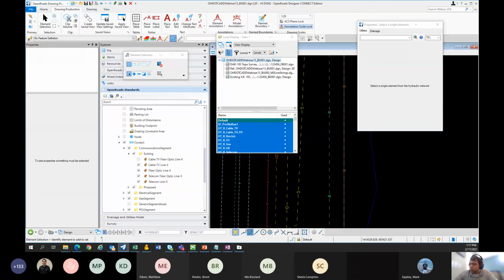Are you saying where you don't want it to show at the center of what it looks like at the center? Is that what you're saying? Yeah, JD, I think they're saying since you're extracting from a terrain and the existing is crowned, they don't want to follow that crown. No, the best you could do is go and edit the profile, and make it not do that. This is the best you can do.